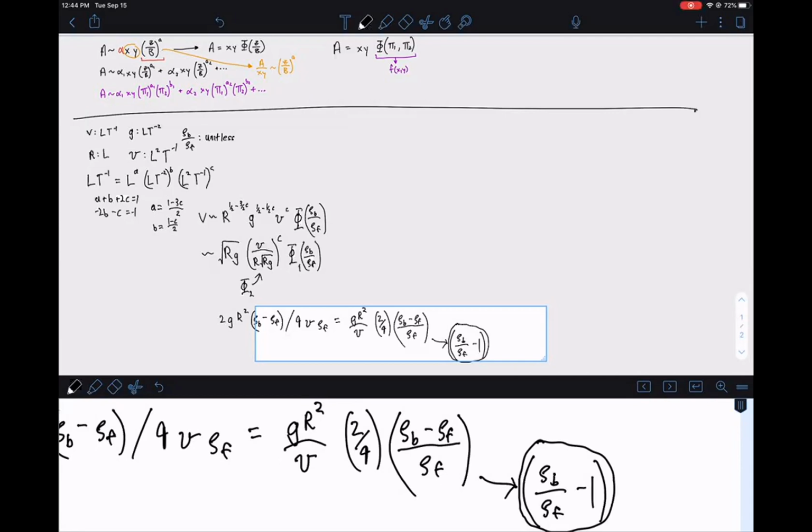Well, I sort of included all the variables like the densities instead of taking a ratio. But then it sort of equaled out in the end where I got a function with two different pi variables. Yeah, that's kind of the point I was going to make, is that the assumption made at the beginning of taking that dimensionless ratio, if you didn't think to do that, if you did your dimensional analysis, it should shake out as a dimensionless parameter in a second pi group, because you have two pi groups here.